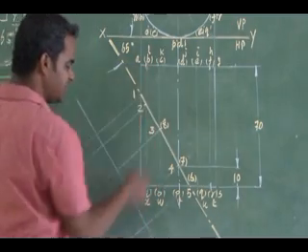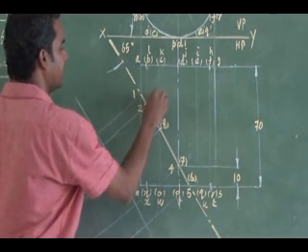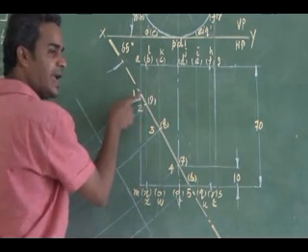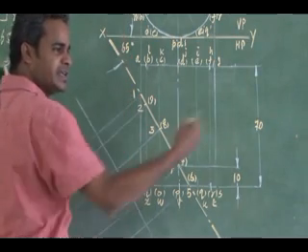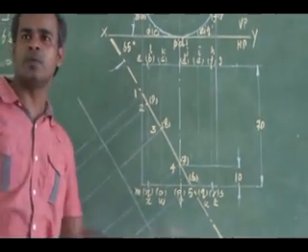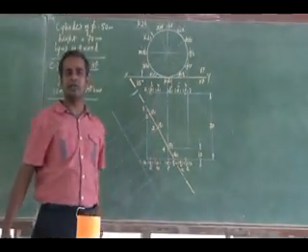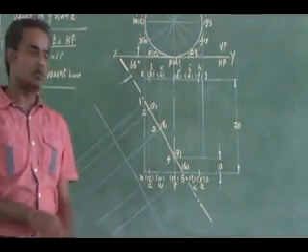Then I have another hidden generator, that is NB, that is my cutting point 9. So again, at the extreme, do you have any hidden generator? Only one generator in the extreme, that is your visible generator, already given a cutting point. So totally how many cutting points do you have? 9 cutting points. These 9 cutting points you project to the front view.